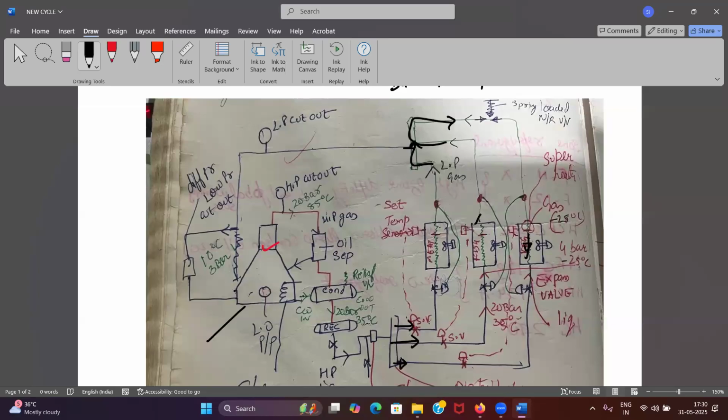And I have explained to you how it is helping by creating back pressure, how it is helping that less amount of refrigerant should flow, isn't it? P2 pressure is increasing, that terminology. Is it clear? Yes, sir. The back pressure station is at the outlet of the evaporator. It is here, on the return line. Look, it is here, the outlet of my evaporator, isn't it? Okay.